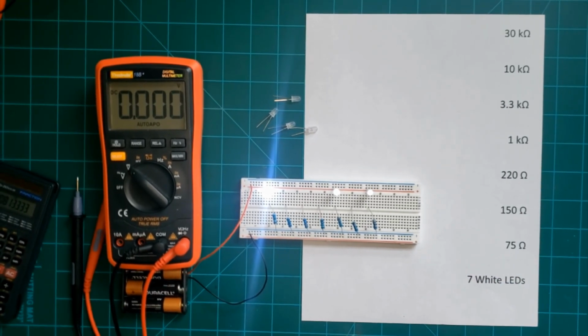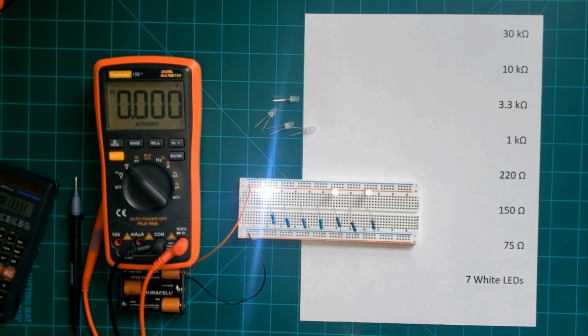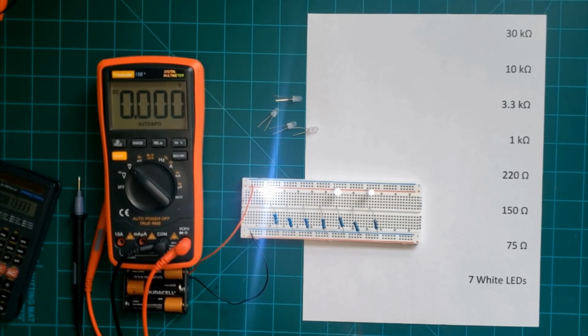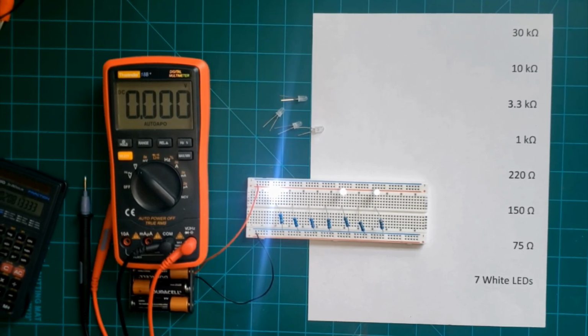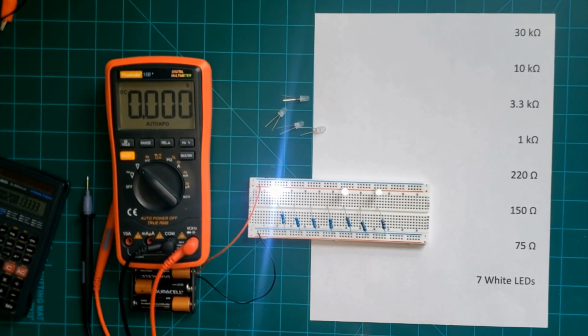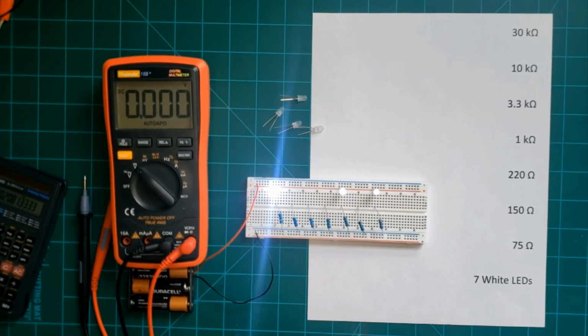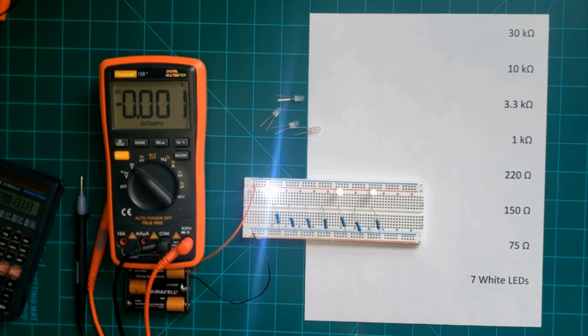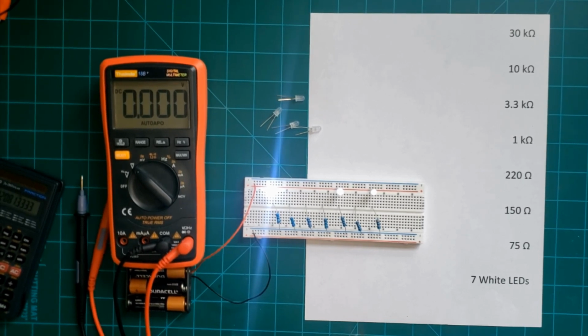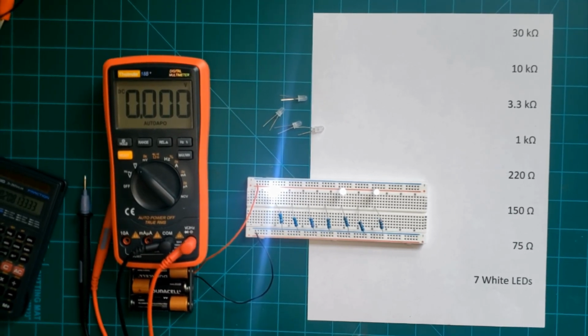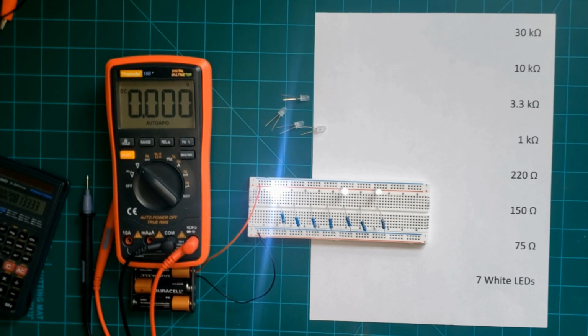So what does this mean to model trains? Well, it basically means that if you want to have a building and you want to have some realism, instead of just always driving your LEDs at the peak value, if you put a resistor, another resistor, or a larger resistor in series with the one that may already be there, you will dim the light.